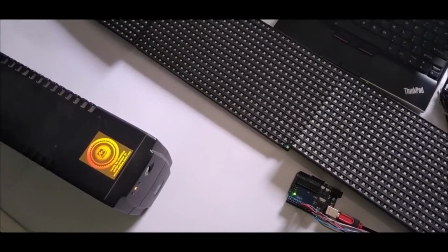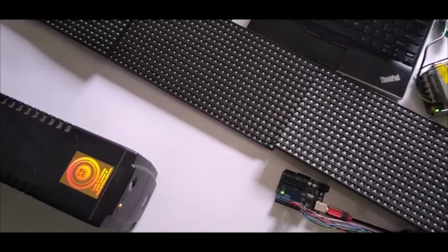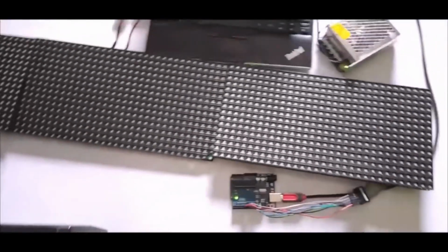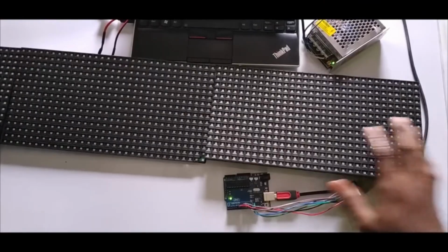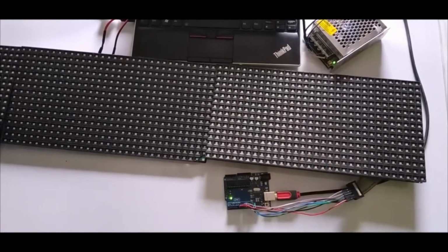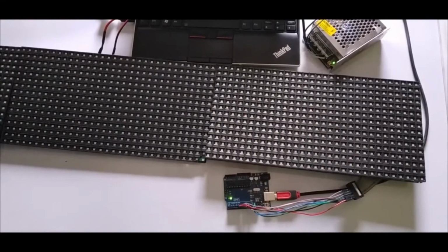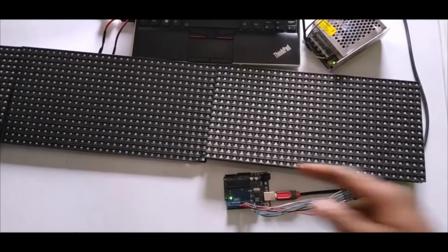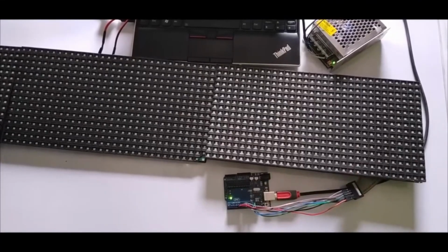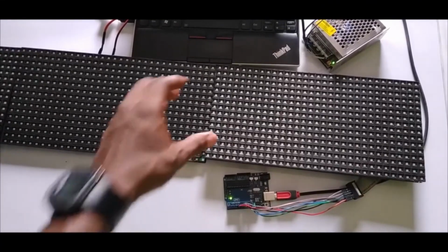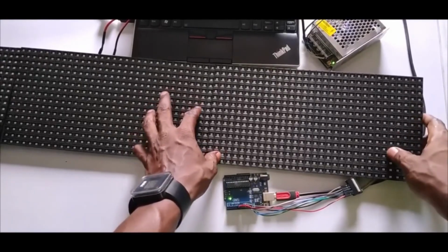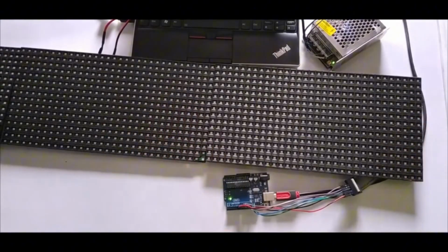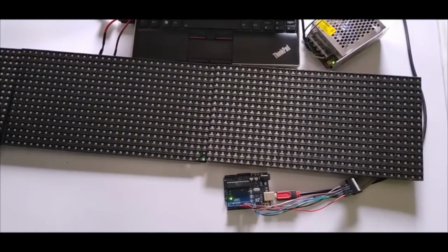So what happens is the UPS supplies power to the power supply, and the power supply in turn supplies 5 volts 5 amps DC to the DMD to light up the LED. So I'll go ahead and upload the code. As the code is uploading, the LED in the Arduino will flicker to show that the code is uploading. And when it is done uploading, the text will start scrolling on this P10 Dot Matrix Display. So let me go ahead and upload the code.